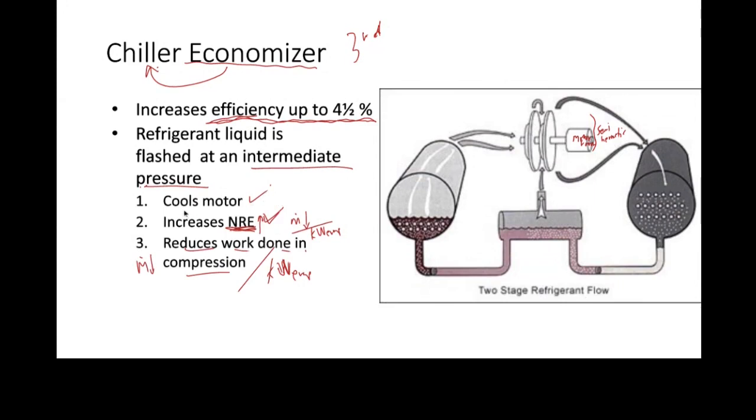There's one other thing that we should look at here, and I'm going to add this: isothermal compression. Now, we're not going to achieve isothermal compression, but we know that adiabatic uses a lot of energy, in particular because we retain the work of compression with the compressed gas.